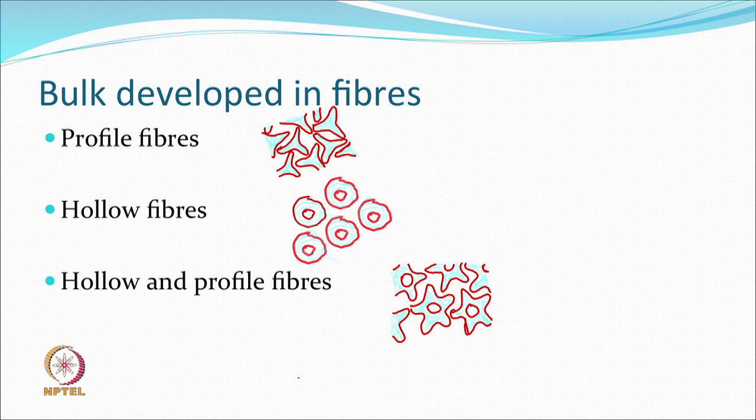So, this we learnt in the beginning also, that if you change the cross sectional shape of any filament yarn, the specific volume per unit weight, per unit mass will definitely be high, and so you can say we are developing bulk. There is no stretch here, but you will still be able to see that the same density of a material, same GSM of fabric will appear bulkier, just because you have introduced a different cross sectional area. The cross section could be whatever, trilobal, pentalobal, hexalobal, octalobal, and all of them will keep changing the whole bulk process. That is the interesting part of it.